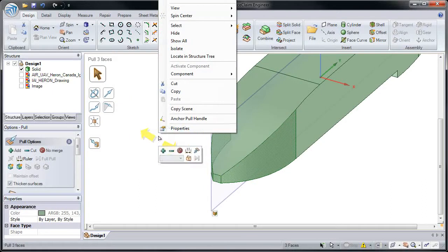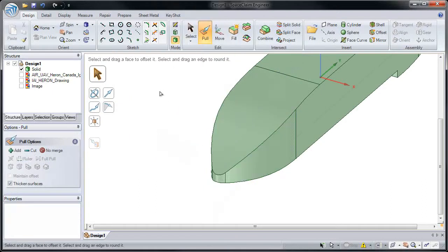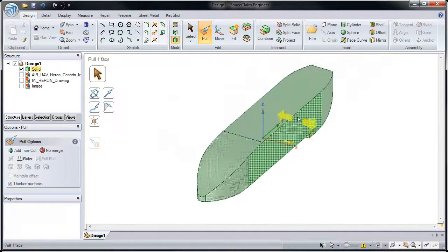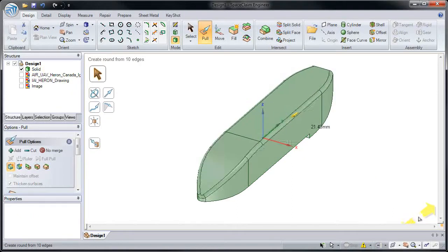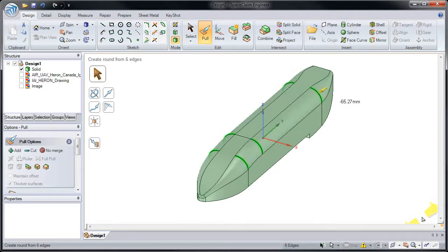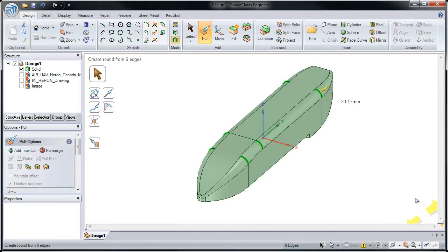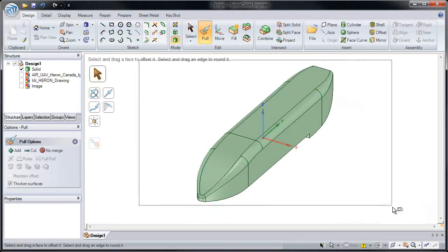And look how fast changes are made in SpaceClaim. We can add full rounds, or simply round any of the edges as we saw previously by selecting the edge to change and changing it. But considering this is a fuselage, we may need to further edit this round. We can edit the round as a whole, or simply edit edges of it to create a variable radius round. This will help the airflow pass over it.